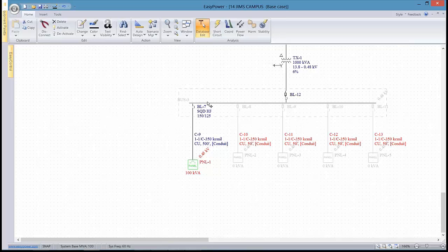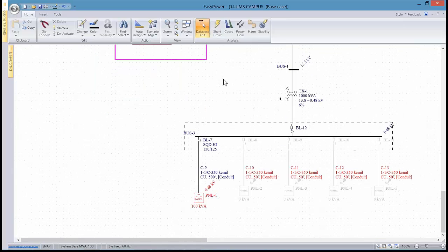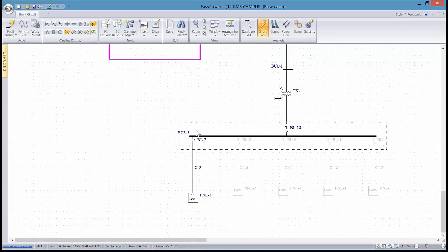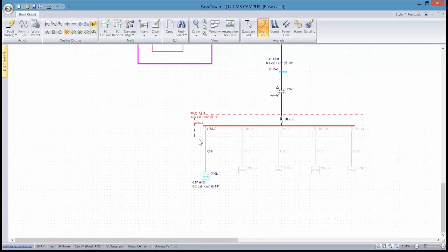and in this case you can see part of my problem is I isolated this bus. One of the things I want to get to a point that I understand all the data that's required to produce this label, and it should include this whole chain back up to the utility. And so as I unactivated this bus, you can see it cleared now to be able to do my arc flash study, so I can fault the bus or go to short circuit. So now you can see it's calculating incident energy, and at that point I go into further steps.